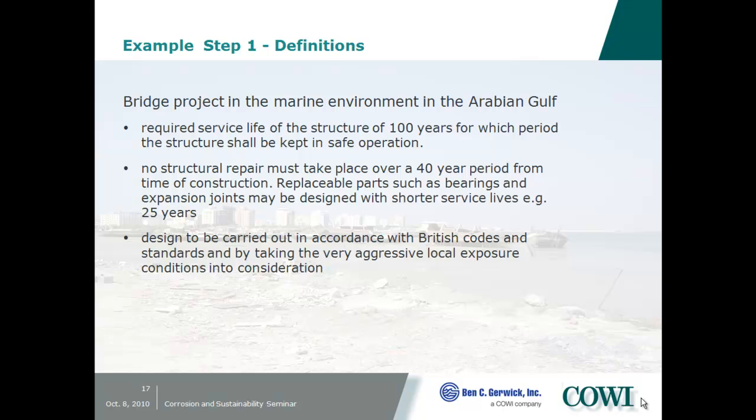And following all of this, I'll give you an example on pricing life cycle costs on this. This is based on actual results, different designs for marine environments in the Arabian Gulf. So that could also be a very aggressive environment here in the States. Required service life 100 years, and of course the structure should be kept safe. A minimum of repair works and some requirements to codes to be used.